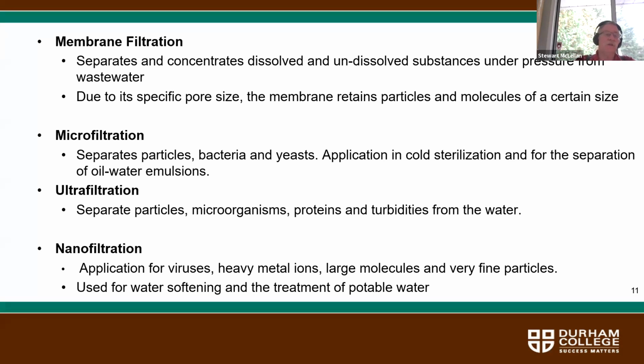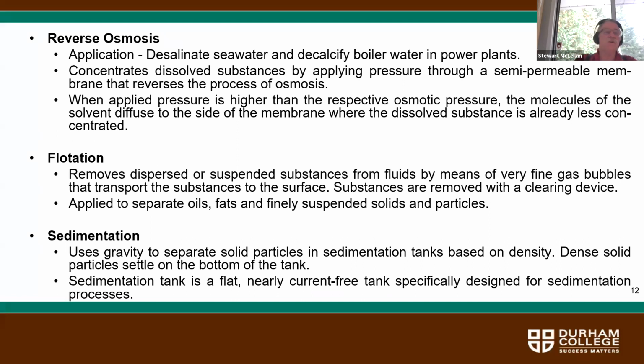So you can see that you have various steps of membrane filtration, from micro, ultra, and nanofiltration. Each one of those systems targets solids of various sizes. Reverse osmosis application, commonly found to desalinate seawater and decalcify boiler water in power plants.